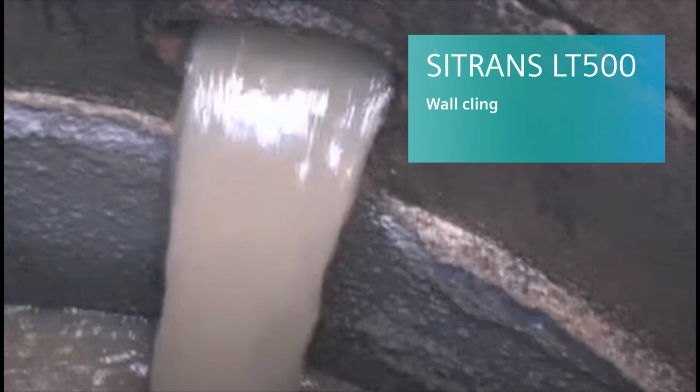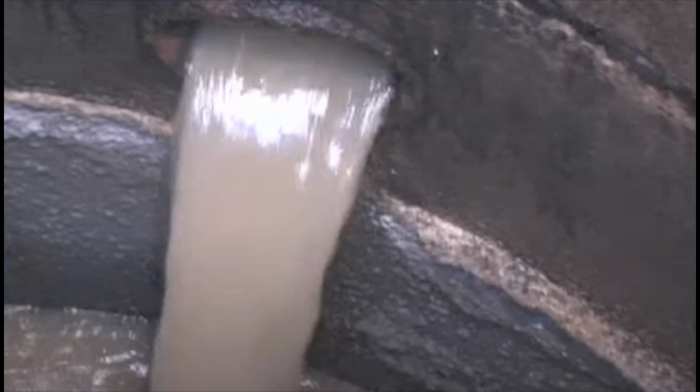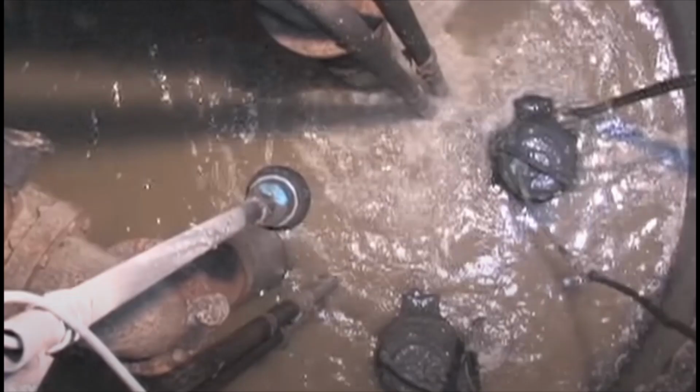Wall cling reduction introduces a variance into the level on and off set points. This helps ensure that buildup does not occur on the inside wall of the vessel in the same spot over and over again. By changing the on and off set points, we ensure that buildup does not occur in the same spot over and over again, creating an obstruction which could be seen as a false reading. We also reduce the maintenance on the inside of the vessel, increasing safety.